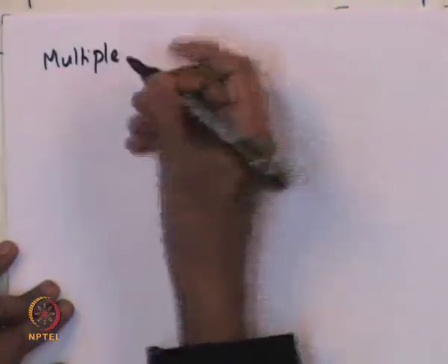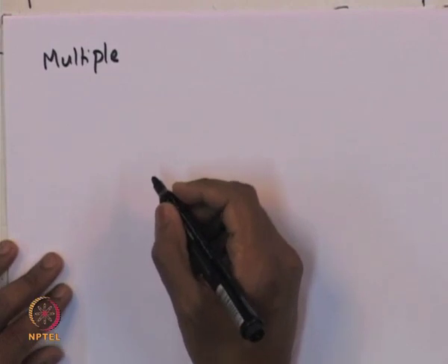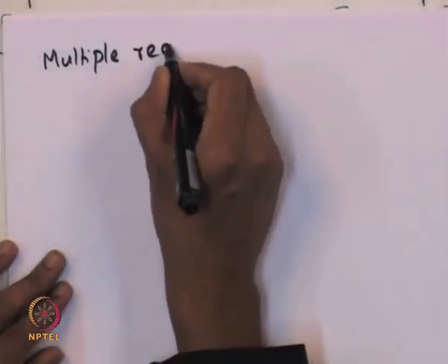So, now we have looked at a single reaction case. Is it possible to extend it to multiple reactions? In reality, many reactions can occur simultaneously. There can be sequence reactions, sequential parallel reactions, etc. Several reactions can happen simultaneously in a reactor. Is it possible to predict conversion when there are multiple reactions happening inside the reactor? The answer is yes, it is possible. It is very simple to extend the segregation and the maximum mixedness models for multiple reactions.